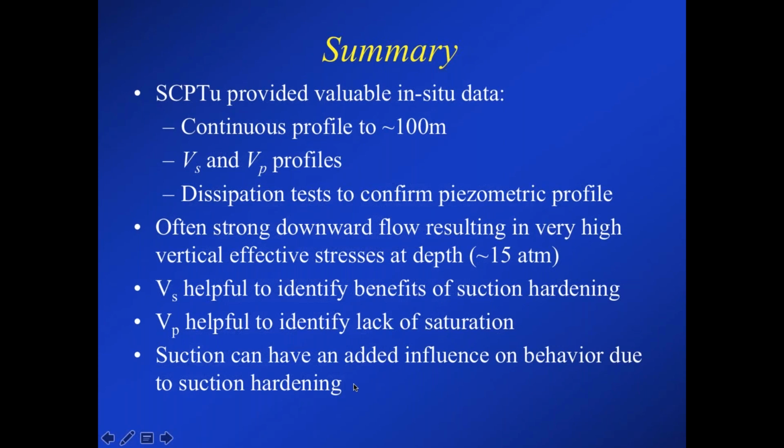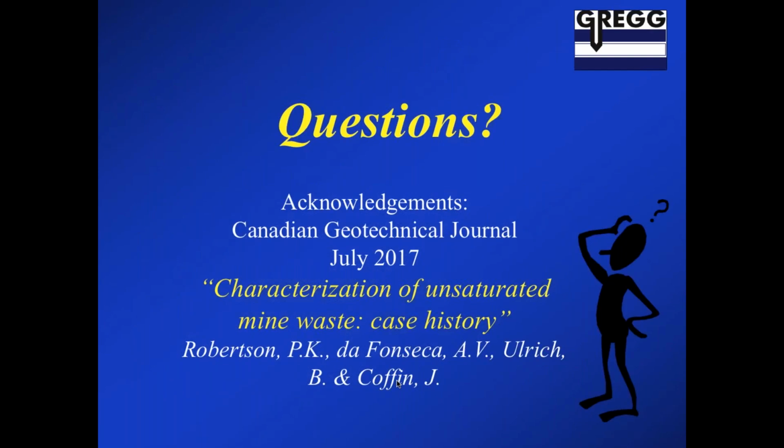And so suction can have an added influence on the behavior due to this suction hardening beyond just the actual effective stress, because this is a relatively sandy material, and so the suctions are not overly large. And so once you're below the upper 5 meters or so, the change in effective stress due to those suctions is pretty minor, but the influence of suction hardening can be significant.